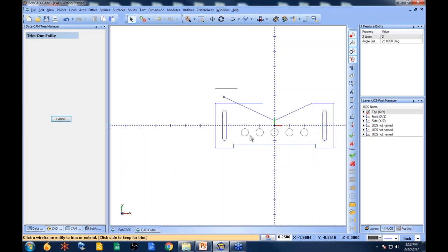That was probably a lot to take in, but it is recorded, so you can play it back. But again, using those coordinate systems can be pretty powerful. If you wanted it to be along an X, we can do a parallel line and trim to it. If we want it to be along that line, you have a little bit of work to do there. I know there is a request in to be able to click on an entity and change the length of it, so you won't have to go through the coordinate moves. But hopefully that answers that for you.